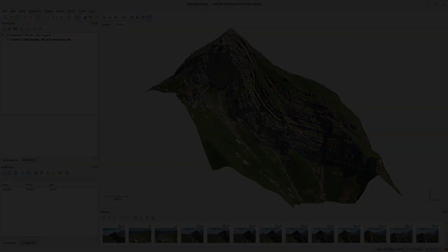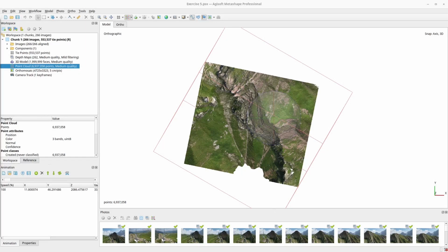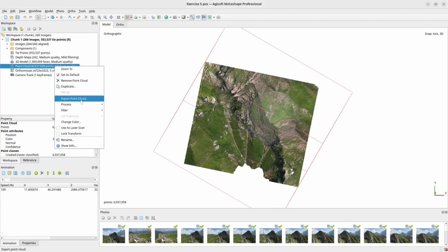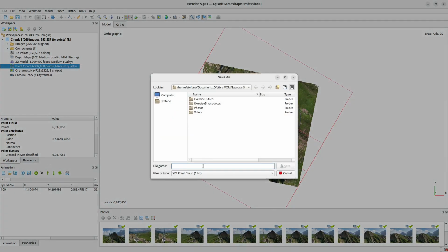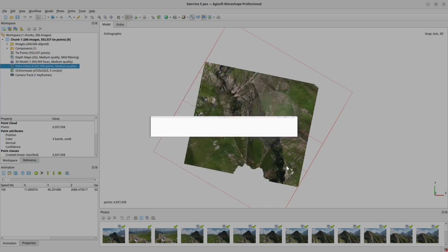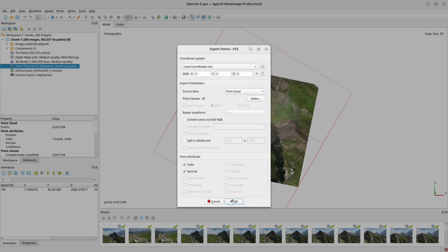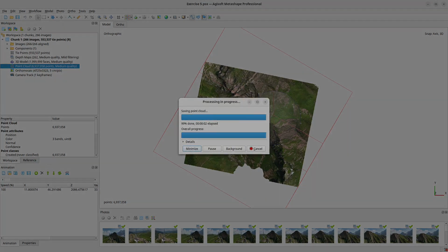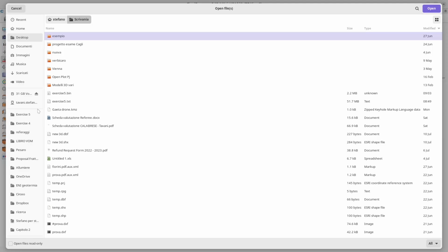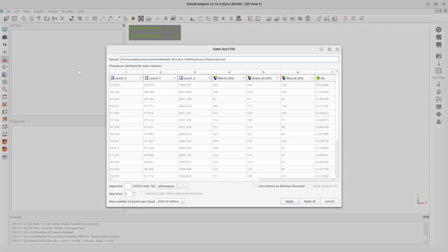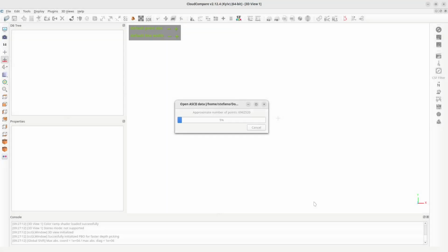An alternative to the illustrated procedure of manual digitization of geological surfaces is their automatic extraction from the point cloud. To do that, we will use the software Cloud Compare. First, we have to export the point cloud, including the normal to point field. The point cloud is then imported in Cloud Compare, where we will apply the Facet plugin.